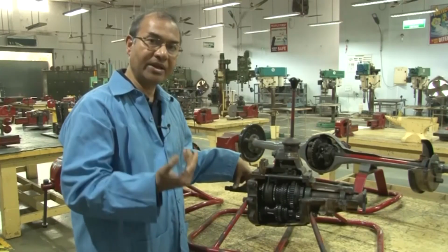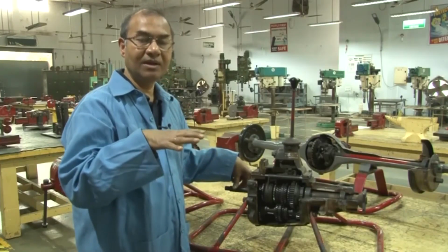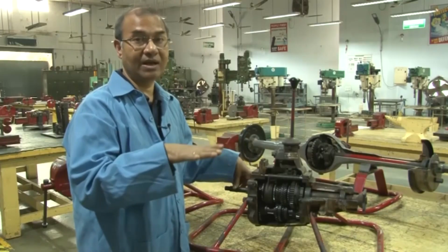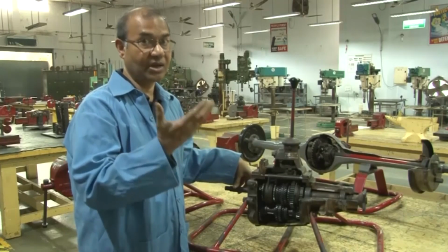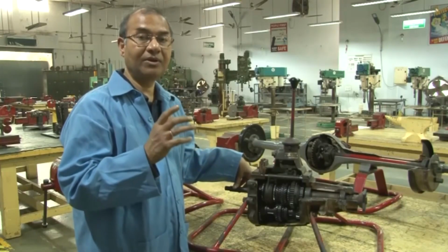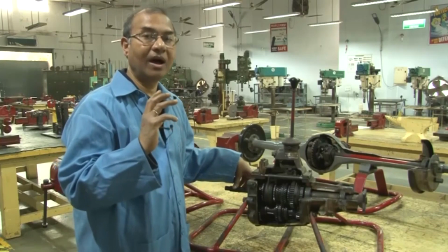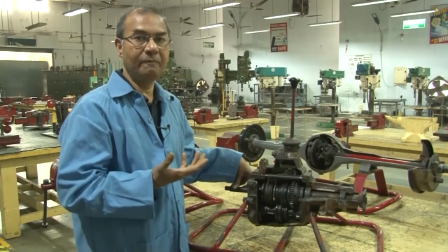So, at the lower gear, when the car is just starting, you have to overcome the friction between the tire and the road, and the car is very heavy. So, that friction force is very high. You have to overcome that, and because of that you need a very high torque, but your RPM or speed should be low.